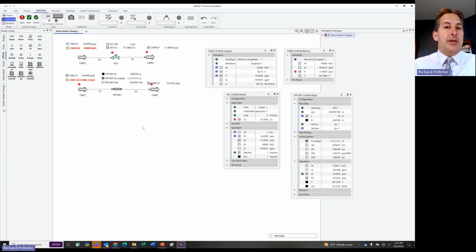But when you do dynamics, that's a time dependent phenomenon, so you can't make that assumption. You have to also include the possibility that there's accumulation in the unit or that there's loss, like a leak or something. So those additional aspects need to be accounted for in the mass balances. If we think about it in terms of the software, when you're in process mode, your models have certain equations that are based on certain assumptions that we can make because we're operating as a steady state sort of operation.